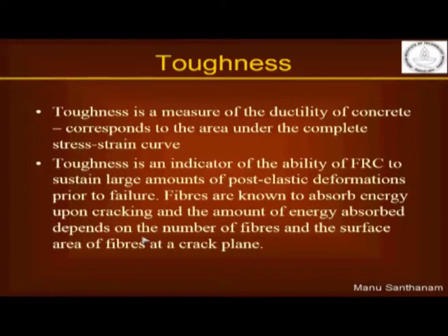Okay, now we have looked at basic mechanics before. When we talk about materials like metals, we measure the area under the stress strain curve, and we have the area until the elastic limit. We call that the modulus of resilience, right. You might remember that we also say that the area under the entire curve is called the modulus of toughness. Similarly, in concrete also, the area under the stress strain curve can represent the toughness of the concrete.